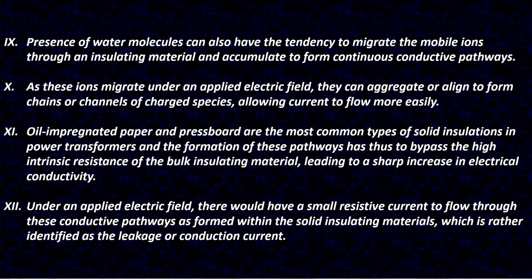The presence of water molecules can also have the tendency to migrate mobile ions through an insulating material and accumulate to form continuous conductive pathways. As these ions migrate under an applied dielectric field, they can aggregate or align to form chains or channels of charged species, allowing current to flow more easily.